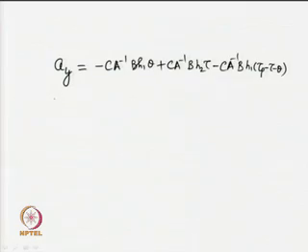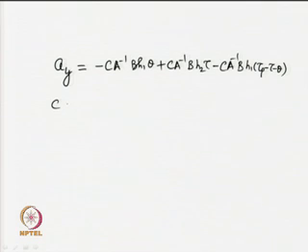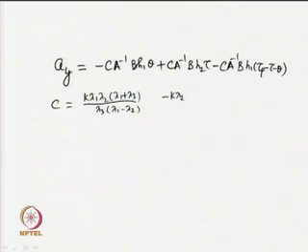We know that from the state space model of the second order plus dead time transfer function model, we have obtained C. C is equal to k lambda 1 lambda 2 lambda 1 plus lambda 3 upon lambda 3 lambda 1 minus lambda 2, and the other element is minus k lambda 1 lambda 2 lambda 2 plus lambda 3 upon lambda 3 lambda 1 minus lambda 2.